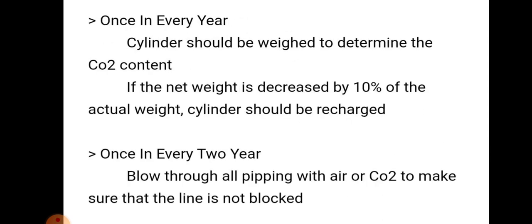Once in every year, cylinder should be weighed to determine the CO2 content. If net weight is decreased by 10% of the actual weight, then the cylinder should be recharged.